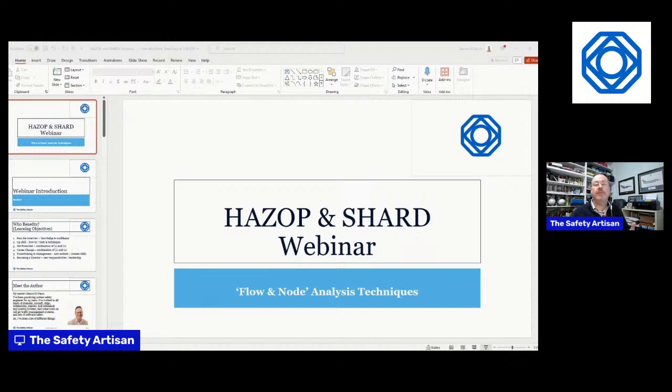Now, the HSE suggests that you should first identify major hazards and check for the availability of hazard data that you want to look at. Now, having said that, you can do a simplified HAZOP to identify the hazards in the first place. It's sometimes called a HAZID or a HAZOP 1. So you can do a multi-stage HAZOP.